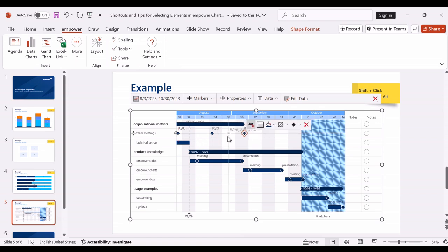I will now show you what happens when Shift or Alt is pressed while moving an element using this data label. This data label is currently poorly readable, so I want to move it. To do this, I select it and move it by drag and drop. If I hold Ctrl or Alt while moving, I can move the data label freely. If I hold Shift while moving, the movement takes place at right angles. This means that the data label can only be moved in this or that direction, meaning at a right angle to the starting position, no matter how I move the mouse.